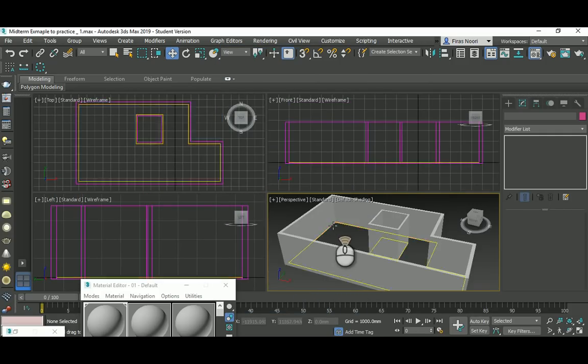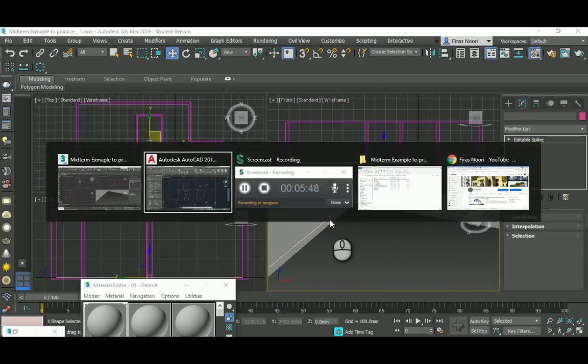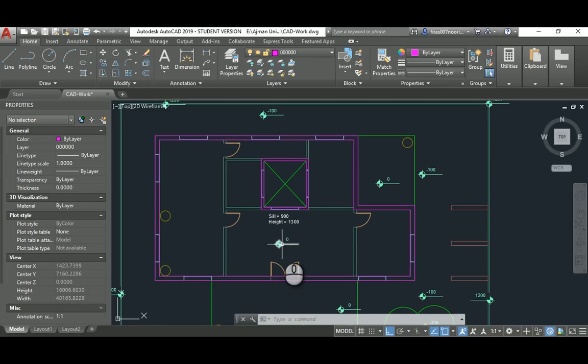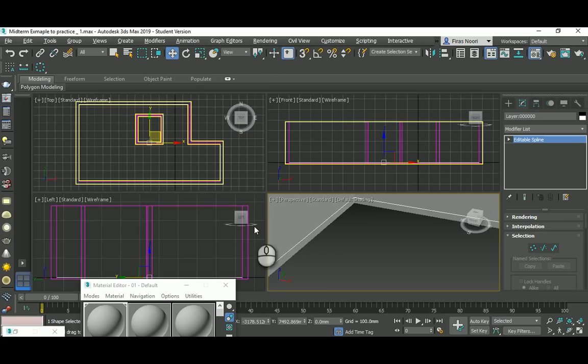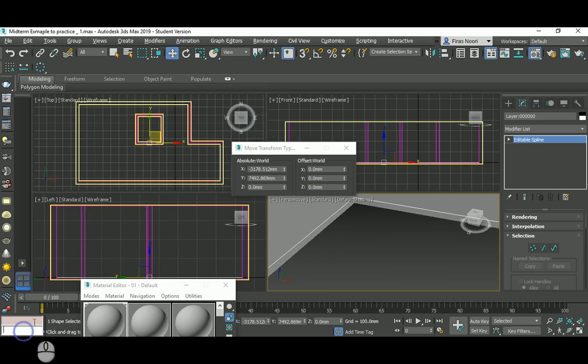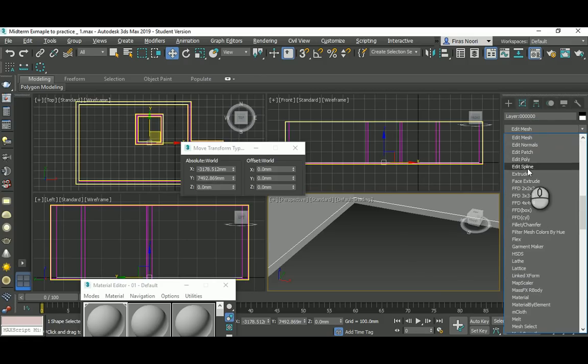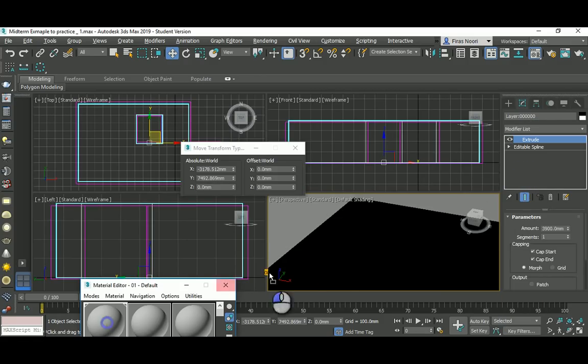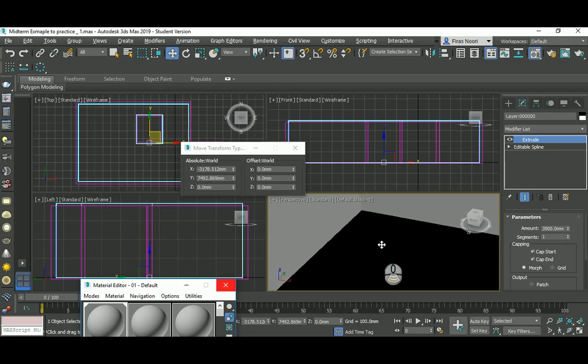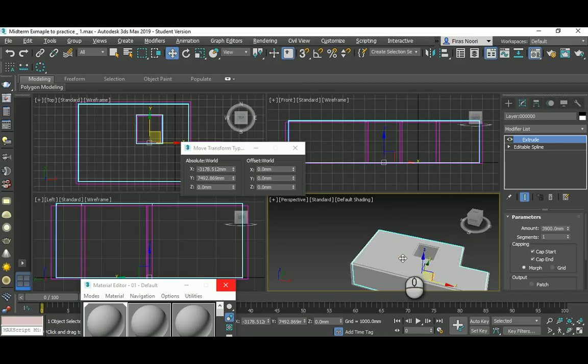The slab is a horizontal element, and the basic rule for it is to follow whatever level you have here in the floor finish, so it's 0. If it's 0, nothing needs to be changed. Then hit extrude and give it a material, and the thickness should be minus 200 millimeters. What happened here?